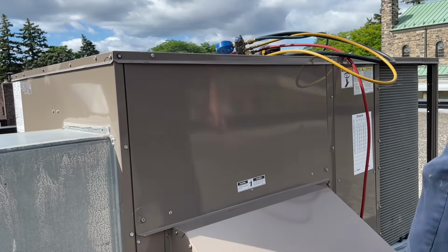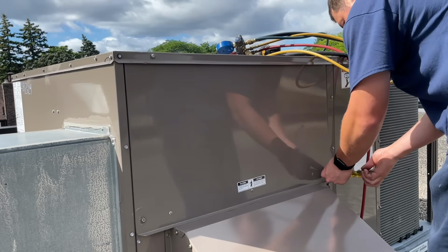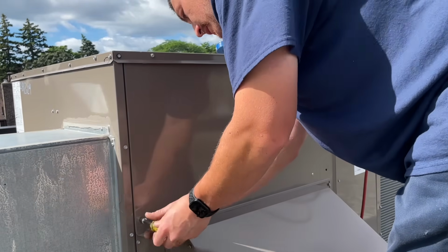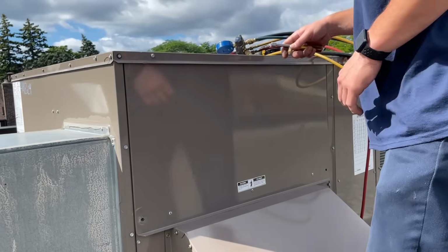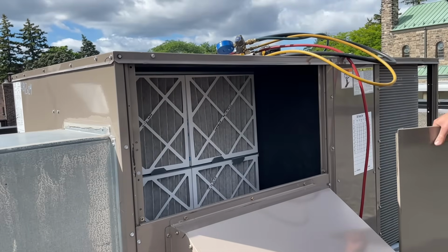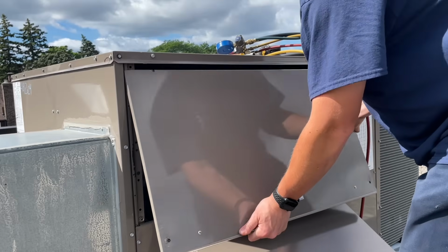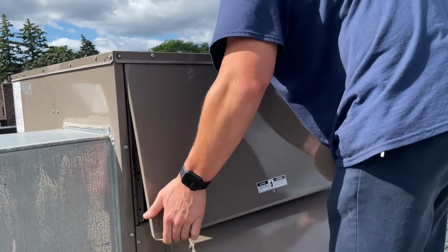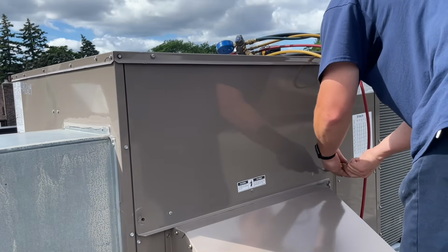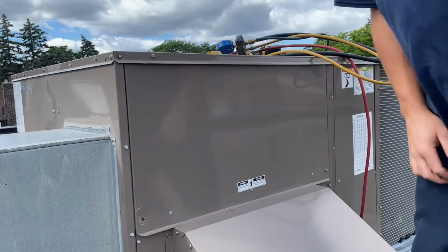All right, before we go talk to the customer about replacing this blower motor, let's check the unit here, the brand new one, that visually appears to be running fine. I just think that it's trying to compensate for the other rooftop being down, and that one's probably twice the size of this, so it can't do so. But let's check our filters. Yep, they were changed on the same date, April 16th. They don't look too bad. I feel this door being drawn on, which is a good indicator that our blower is working properly, because we're on the negative side of the unit here. So we'll throw this back, and next we'll check our cooling levels.